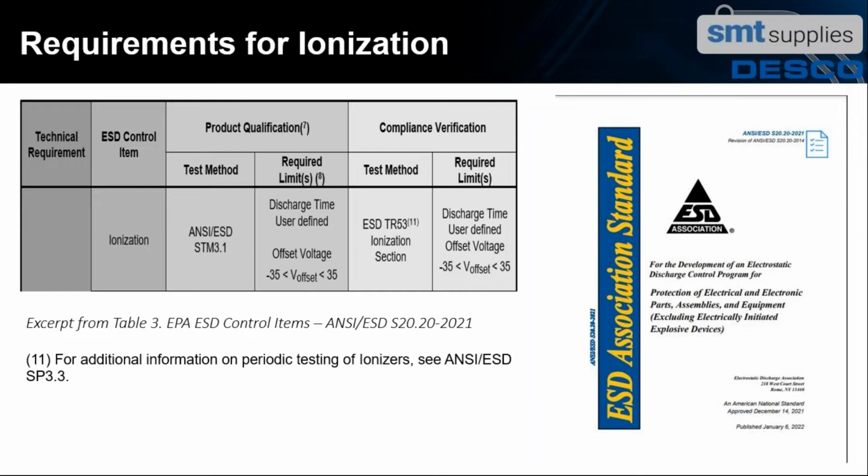So when the ionizers blow out positive and negative ions, if the ionizer is blowing out an excess number of either one, positive ions or negative ions, then any ungrounded devices in the airflow of that ionizer can be charged to that polarity which had the excess.